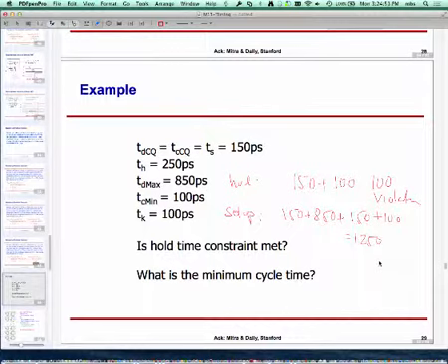So again, in this particular case, we were really not given any other details. There is no circuit given to us, right? So the skew is really referring to that you have to be prepared. Any flip-flop can be ahead or behind. So you're really looking for a worst case.